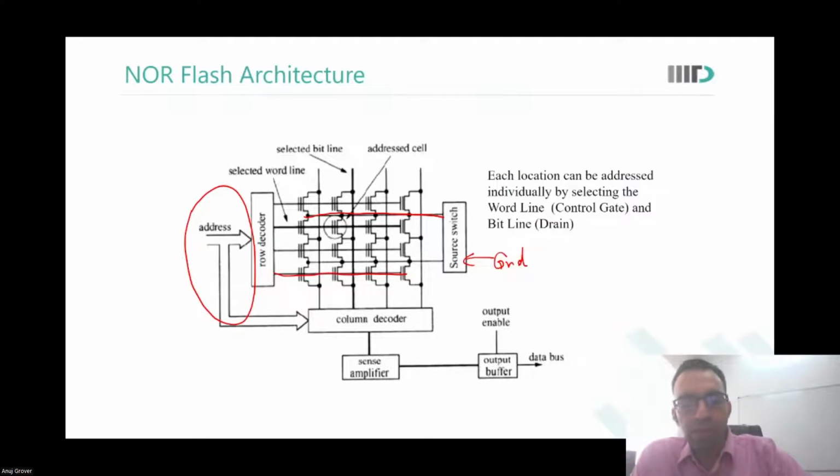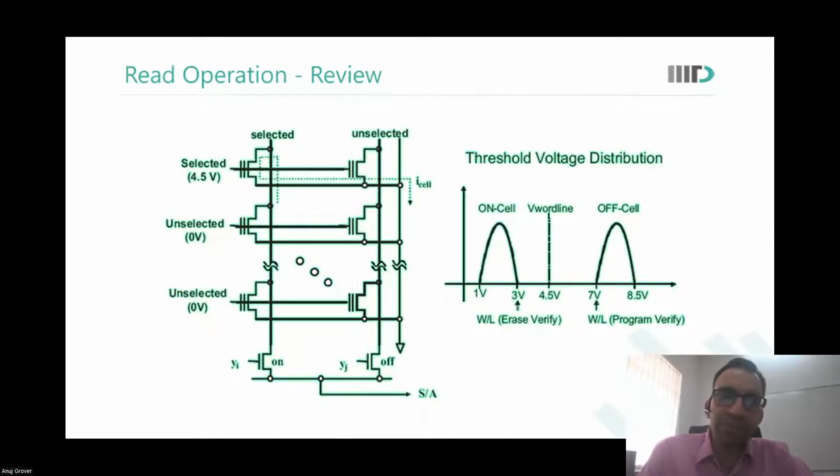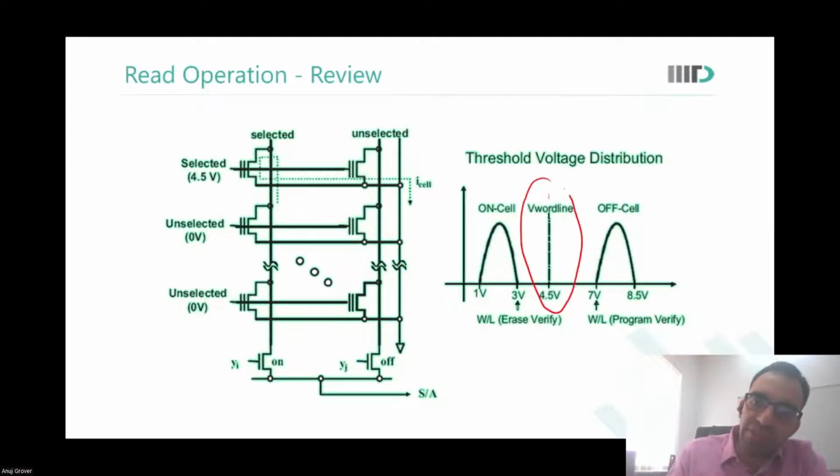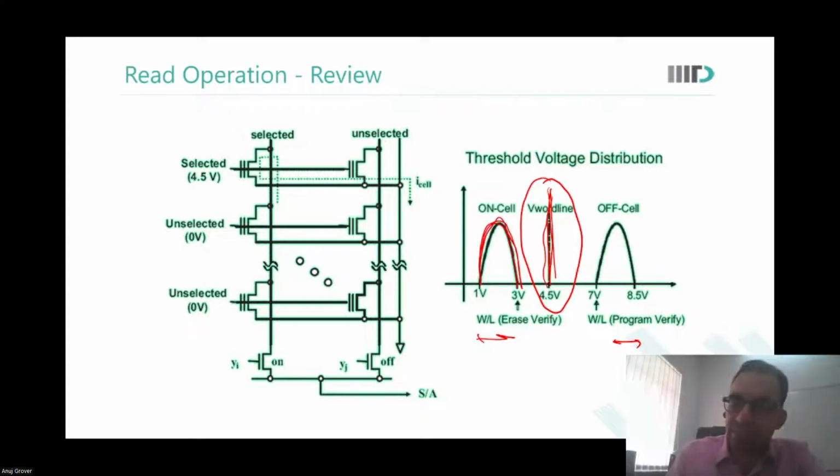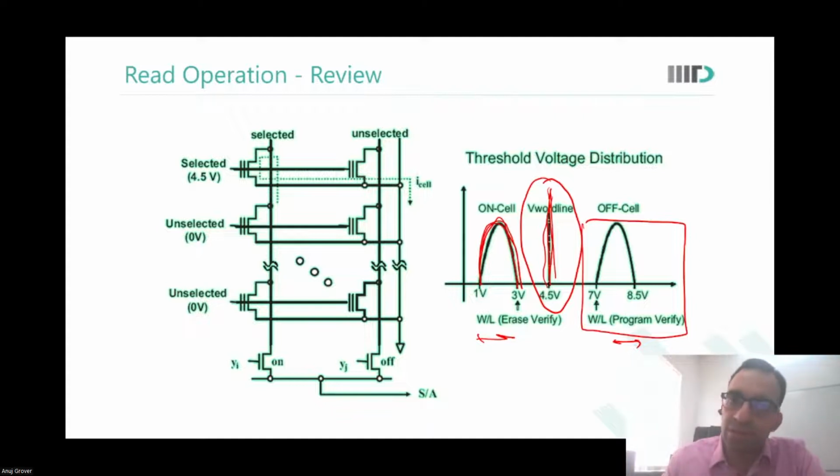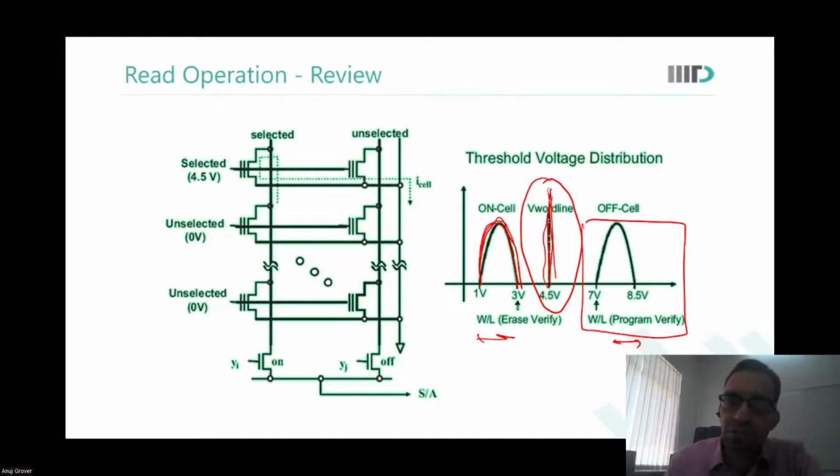Okay. So when we have this NOR flash, to do the read operation, we just take the word line to a level which is between the VT of, say, 0 and 1. At this particular word line level, all these devices will sink current, and the devices over here will not sink current. The cells that sink current are said to have, let us say, 0 stored on them. The other ones are said to have 1 stored on them. Is it okay?